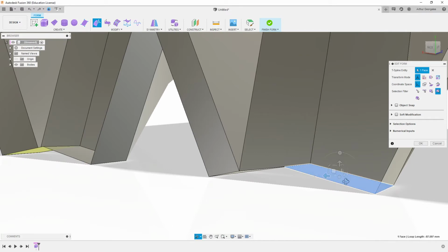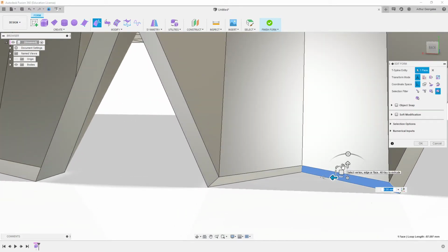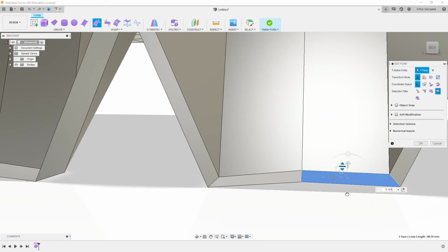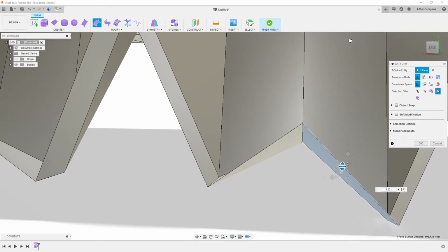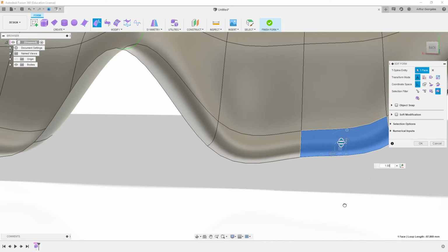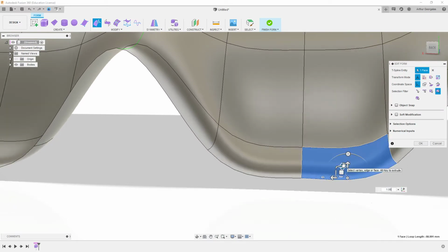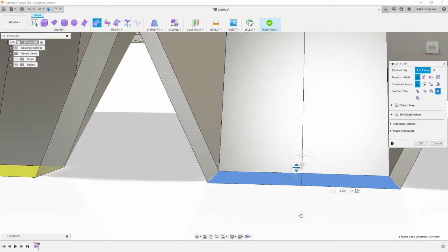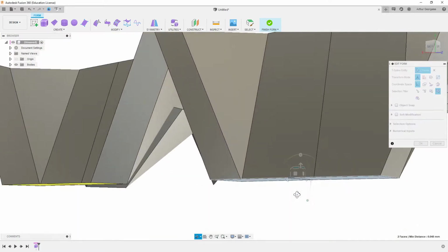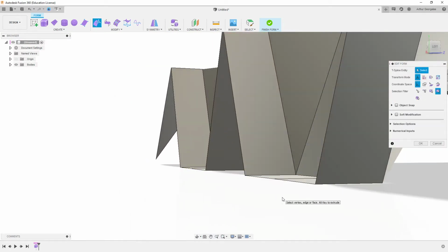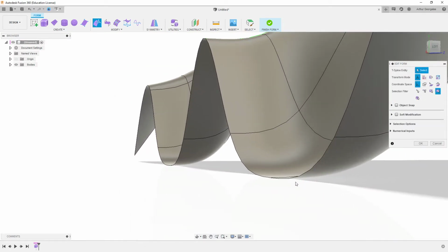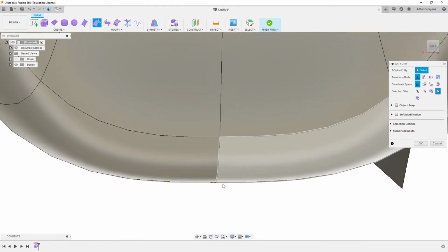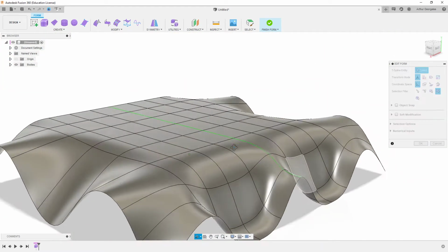There's another way though, we can use the scale feature, and that allows us to pull objects flat or to increase the proportion. So I don't know if it's actually called scale or proportion or whatever it is, but we can select two of these faces and pull this in, and it's going to allow us to flatten it out. It does freak out when that number trips at 0. So you just drag it down very close to 0 and it'll look pretty normal. And there you can see it comes in and transitions back up really smoothly.